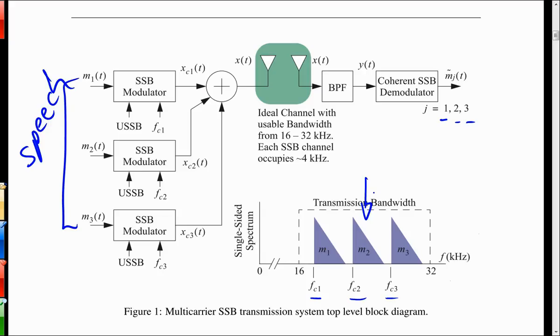Is the spectrum that you can hear from around 0 to 15, 0 to 20K? Well, these messages here are all 0 to 4 kilohertz. Because they're sampled at 8 kilosamples per second, so the folding frequency or the usable bandwidth from sampling theory is 0 to fs over 2.